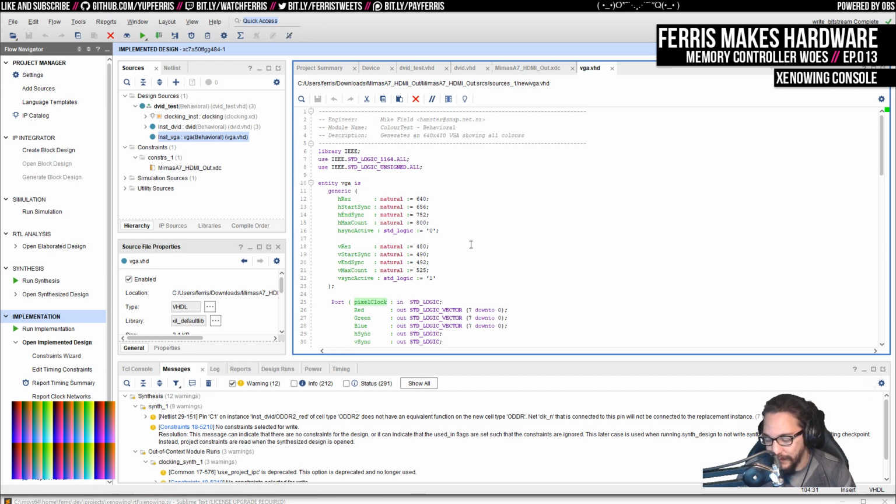If our system runs at 50 megahertz, it's still going to do what I want it to do and make me happy. But probably 100 or whatever is what I actually want. And then if that ends up being 125 to play nicely with the TMDS output, that's probably cool. Really depends. But the important thing is that we need to do this TMDS encoding ourselves. So that's going to be important.